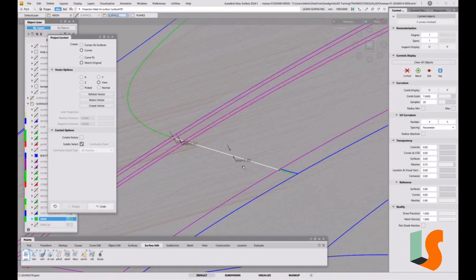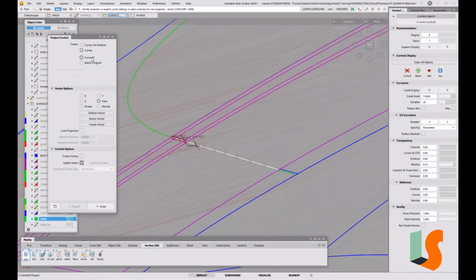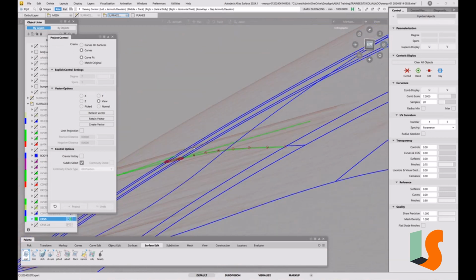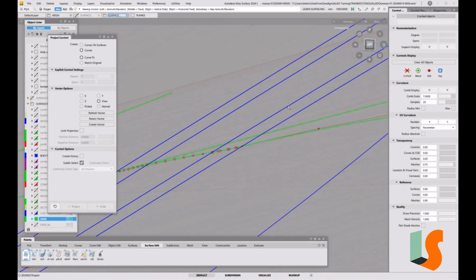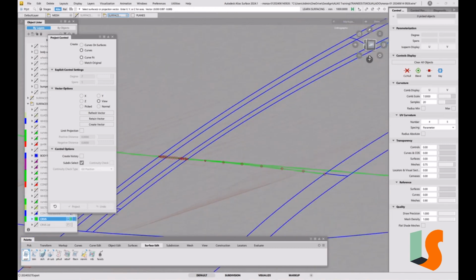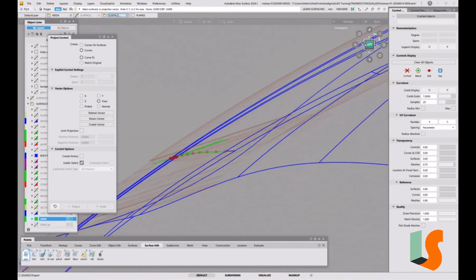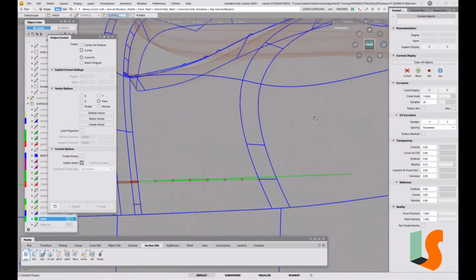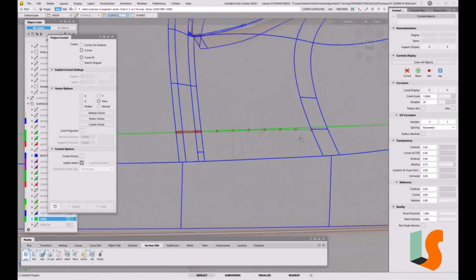So it says maximum deviation 2.35, and that's because it's keeping the degree 1, which obviously we don't want. So we have to do curve fit, and that lets us put in a higher degree. I might as well put in degree 7, then gives us maximum of 0. Now that looks perfectly fine there, but as soon as you rotate it, you will see there's a bit of a dip down, but that is inevitable. We can't avoid it with the shapes that we've got. So that's what we're getting from there.